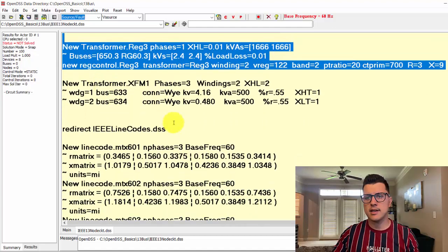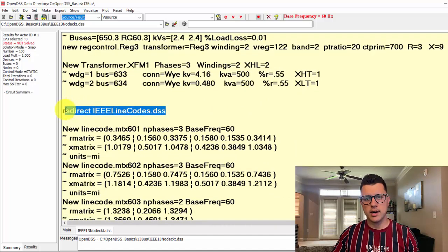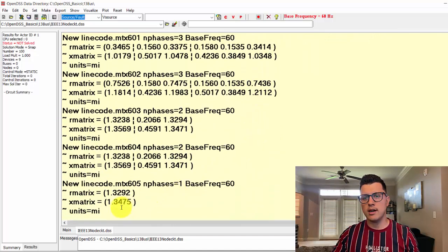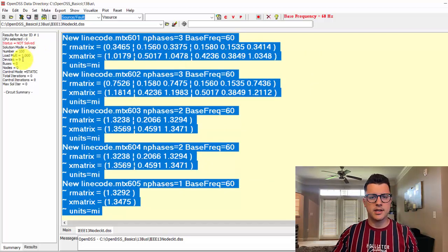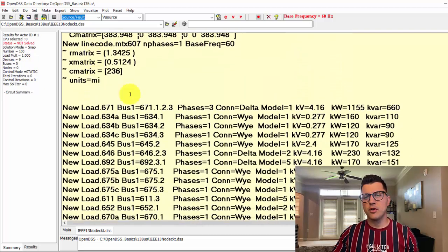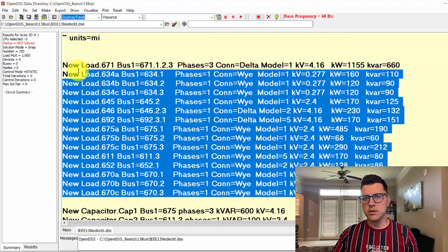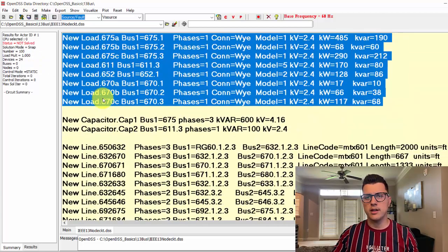We then run transformer, go to 9, and when we run the file with line codes, or even when you run here the line codes, the device's information doesn't change, because those are not devices, those are general elements in OpenDSS. Therefore, here for what we are seeing devices, they don't count. So if I run loads, you're gonna see that we have devices 9. It goes to 24 because we run all the loads.